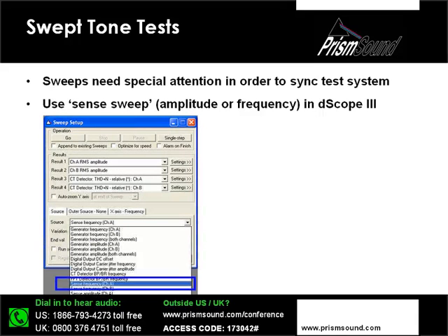So in other words, we are able to sense the incoming amplitude or frequency, depending on the variable of our sweep, in order to be able to complete a sequence of individual tests at either discrete amplitudes or discrete frequencies, and to join them up in a two-dimensional graph to give us an understanding of how our device performs with respect to either amplitude or frequency. Again, that's normally straightforward in the conventional audio measurement sense, where the generator is applied to one of the input terminals of the device under test, but in a playback device, as we saw, this is not possible.